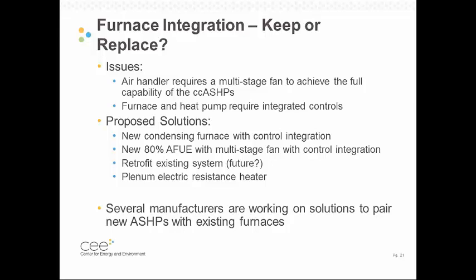So that was one option we considered. Another thing we're starting to see some movement in the market is some different solutions for doing a staged installation. You can just install the heat pump and match it with your existing furnace or backup system, and then when the furnace lifetime expires or dies, you replace that with the newer furnace that has all the features. So you have somewhat non-optimal performance for the first period while you're working with your existing furnace, and then when you replace that furnace, you unlock the full potential of the heat pump.